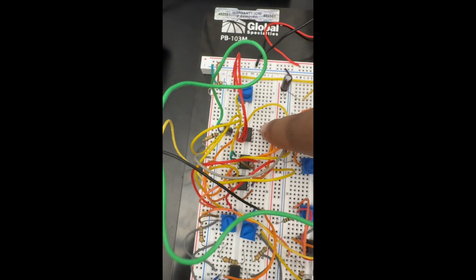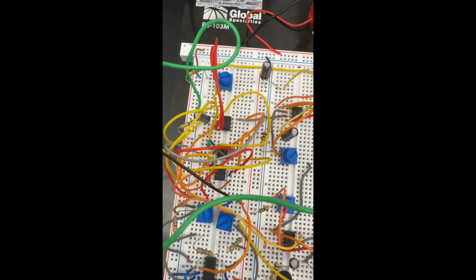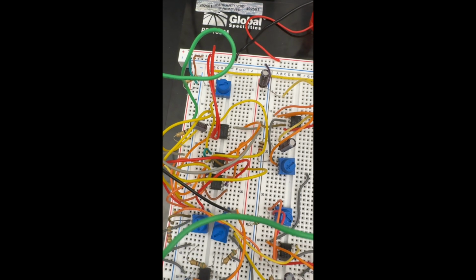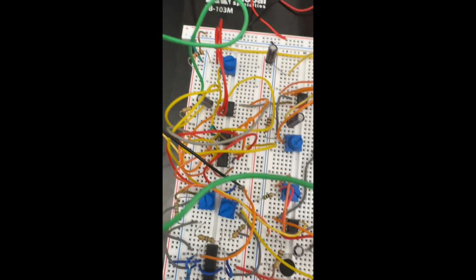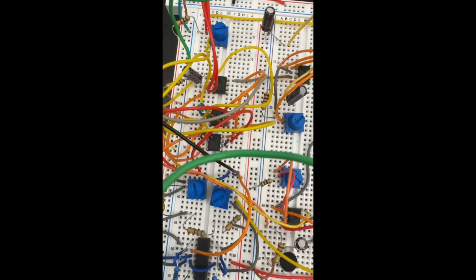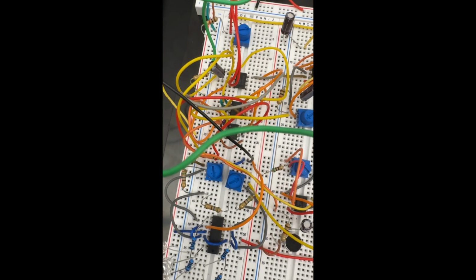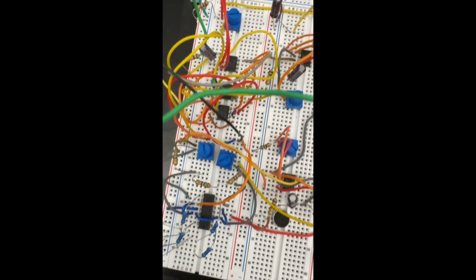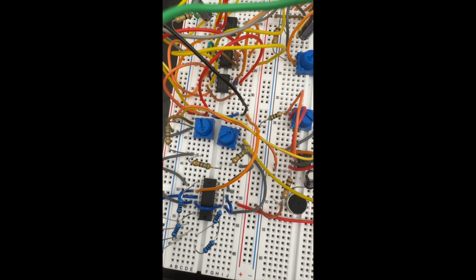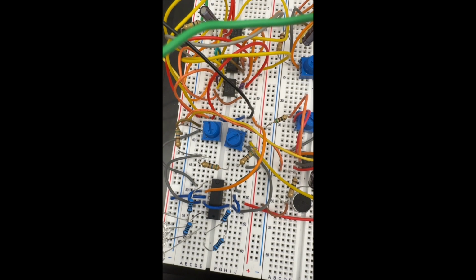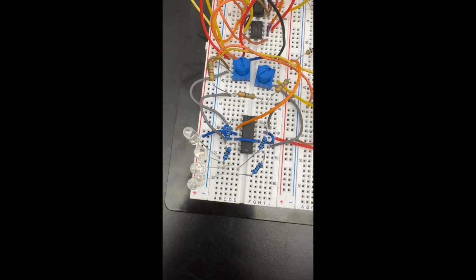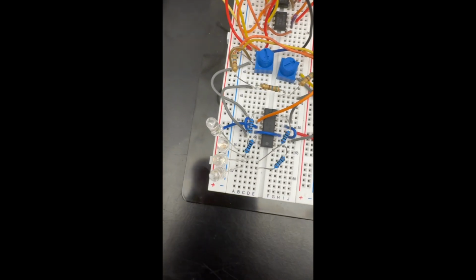This op amp is receiving the information from the laser pointer, the sine wave, and these 2 op amps are buffers that will make the amount of current going into the speaker higher, so that it's playing the noise at a louder volume. These 2 potentiometers are the top and bottom of my voltage divider for my LEDs. This op amp is for my 4-level LED indicator, and those are my 4 LEDs.